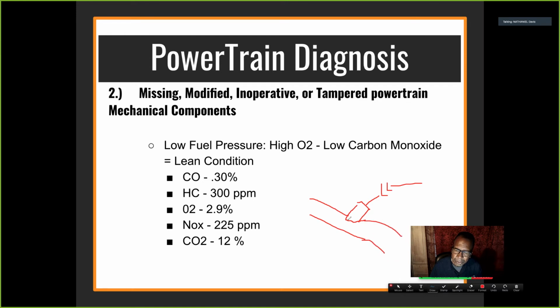It's a very bad draw on the O2 sensor. All right, so this is the O2 sensor. This is a crack in the exhaust. This is the air fuel mixture you're talking about. Correct. Now you're saying that during this process, the air fuel is going this way. The exhaust gas is going out this crack here, right? Yes. Okay. And the rest of it is going past this O2 sensor.